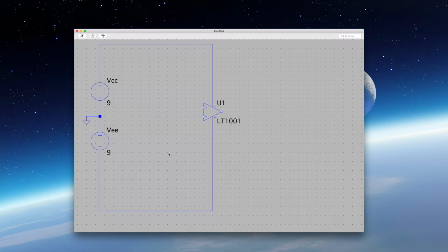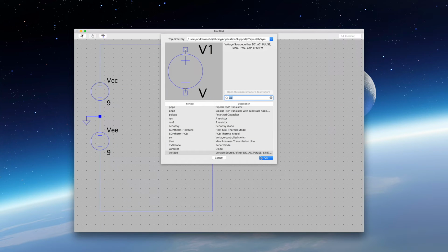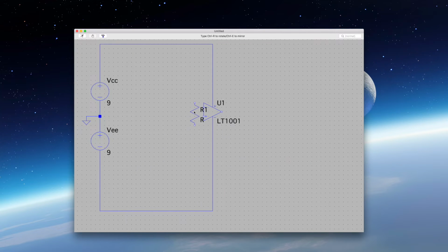So we will use maybe 30 kilo ohm for the feedback resistance, which means the other resistance, the one at the inverting input, will be 10 kilo ohm. All right, well, let's do that. Let's go ahead and get some components. Let's call it resistor. Okay, and I'm going to put this one right here. That's a good place to put it.